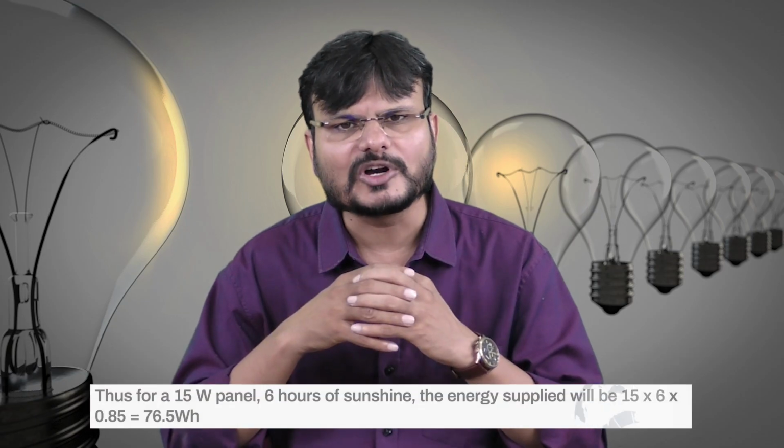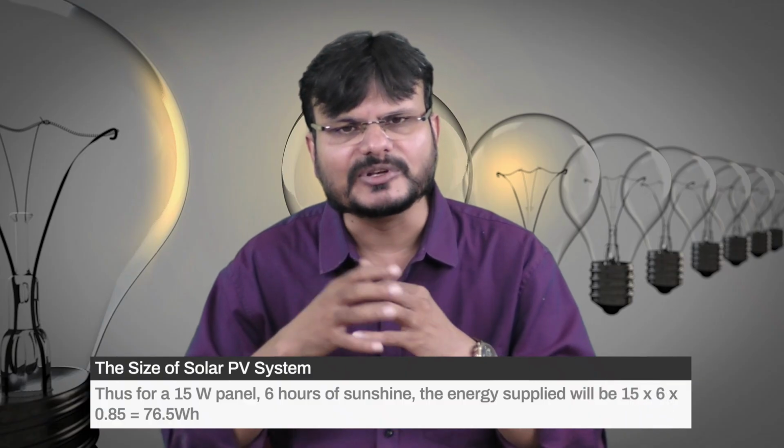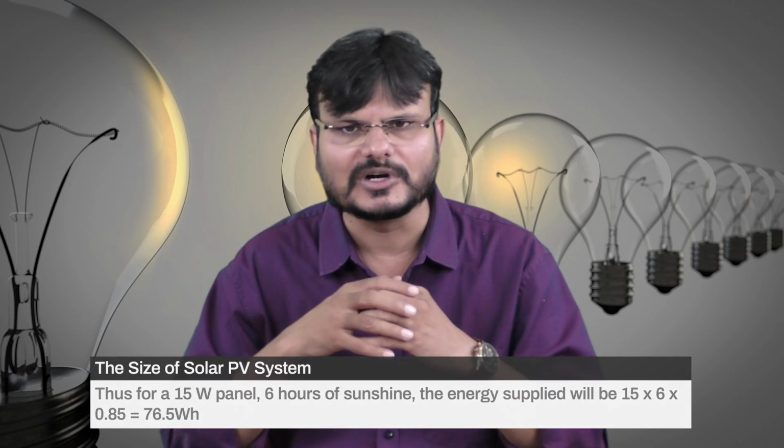Thus, for a 15 watt panel with 6 hours of sunshine, the energy supplied will be 15 into 6 multiplied by 0.85. So it comes to 76.5 watt hour.